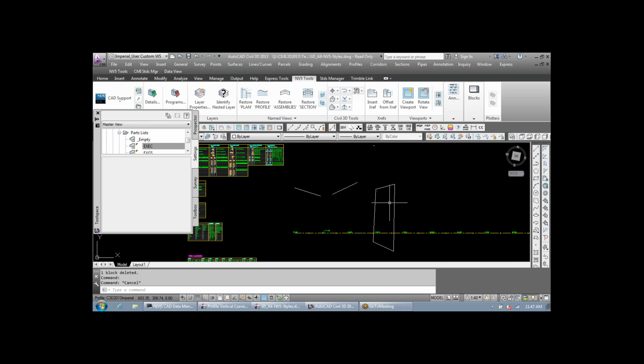If you don't want it to explode, let me know, and I can change that code rather quickly, or we can make one or give an option to explode or not explode. If it's a block already, that's where it's the most powerful. I selected a simple polyline. If you already have a block, it's going to create a block, vertically exaggerate it, and then explode that temporary block. So you're still going to have your original block, and it's going to be exaggerated by 5.